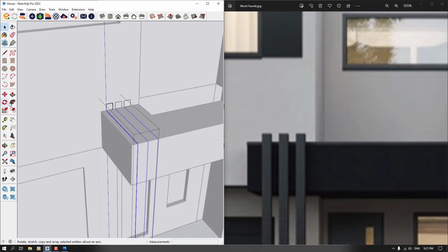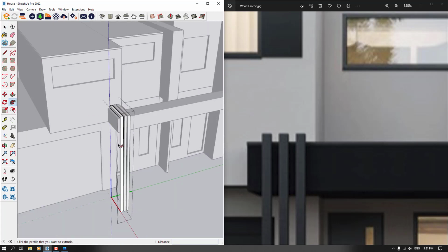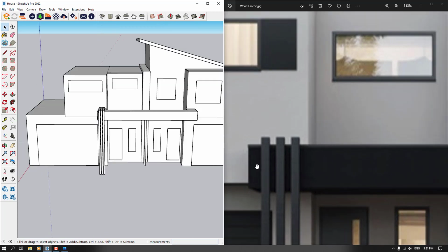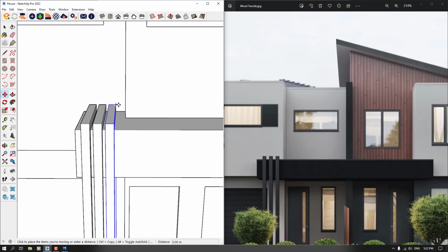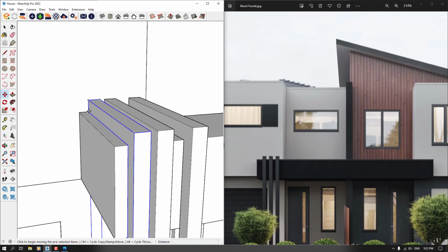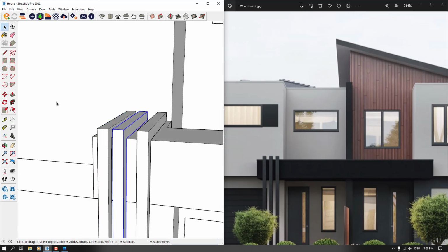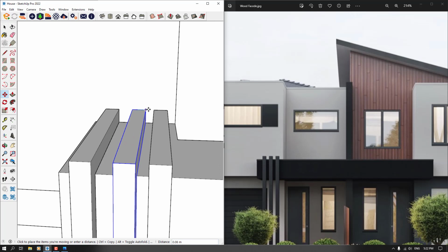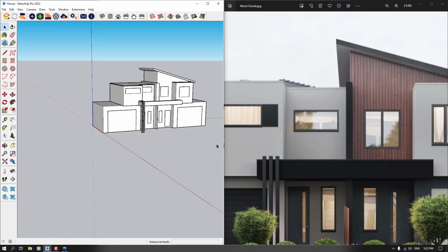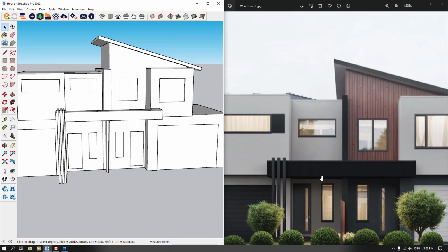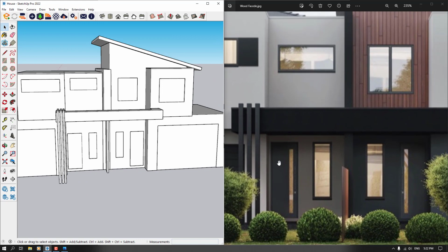I'm going to select my path. I click on the follow me option, and now we have this type of triple lines. Actually they have a little bit distance between each other, about 8 centimeter from here, and I think maybe a little bit can be better, like that or like this. So now we have this model in here. So let's get modeling these type of doors and windows.